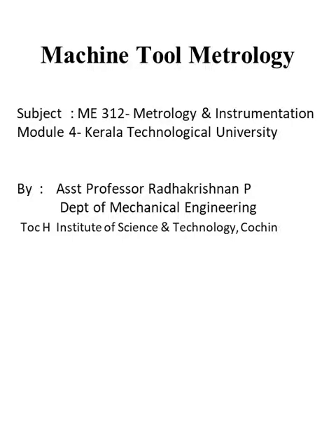Similarly, spindles, which make the components rotate: their concentricity, axial slip, accuracy of axis and position, etc. That is why this machine tool metrology is very important. Various tests are applied before the machine is erected and commissioned.